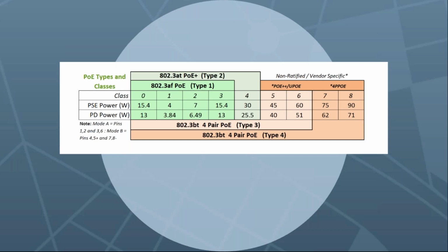It's at 48 volt, technically a minimum of 44 volts, but typically about 48 volts, and would provide up to 15 watts of power. There's a handshake between the power injector and the device it's powering. This prevented units from receiving too much voltage. So if a device was passive, it wouldn't accept that power, so that you could protect your expensive equipment.